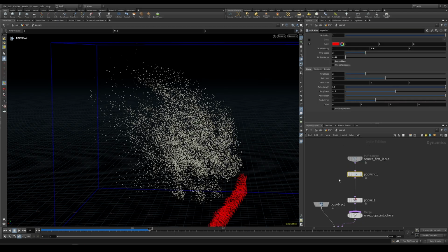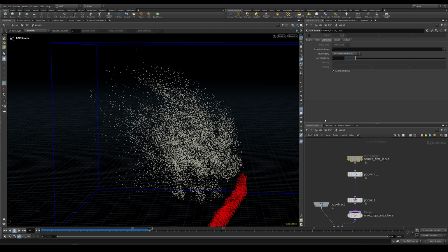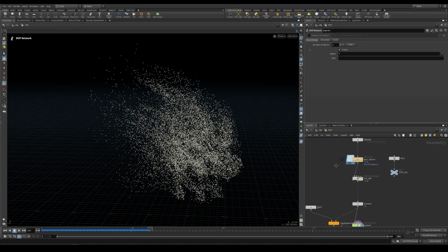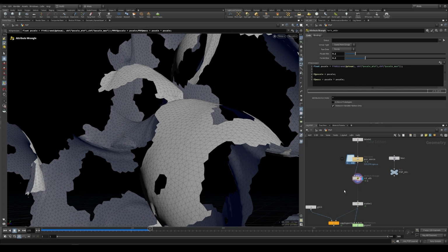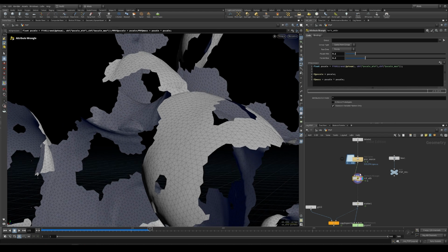Now we want to introduce some initial velocity. Here we are inheriting the velocity, but we don't have any on the points. Now we will introduce both some velocity and some angular velocity on the points, but to do that, basically we need to compute a couple of vectors here in the init attribute. We need the usual vectors that we can use to build some local frame, one pointing outside the mesh and one which is tangent, so we can use some neighbor point for this.